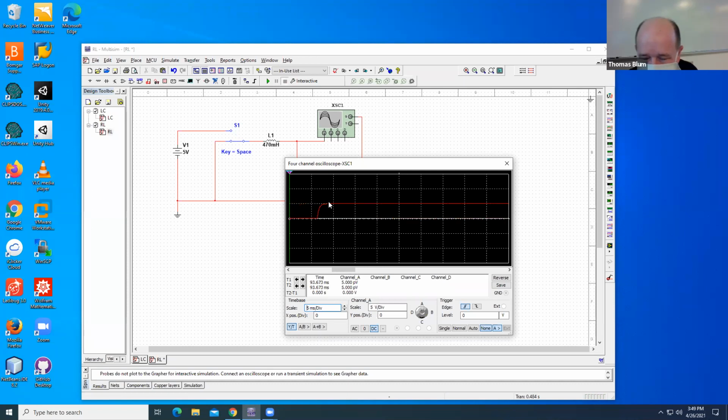It does this curving. And we've seen this form before. This shape should be familiar to you. This is the shape that we saw in RC circuits. And there is a little bit of a corner here, and then it goes up to some saturation. Okay. So I want to change the time constant. I want to stretch this out a little bit because that's the behavior I'm interested in. So I want a smaller time constant, which will stretch it out a little bit. That's probably stretched out enough.